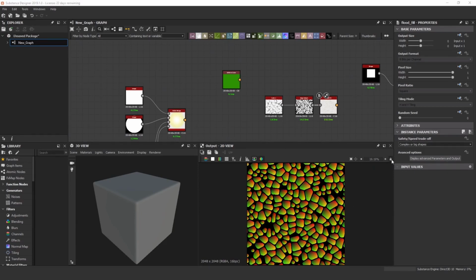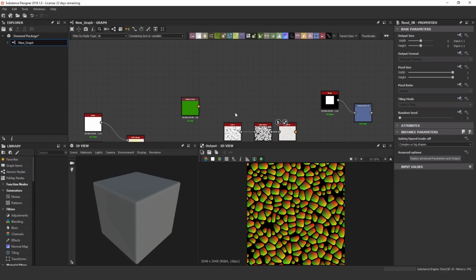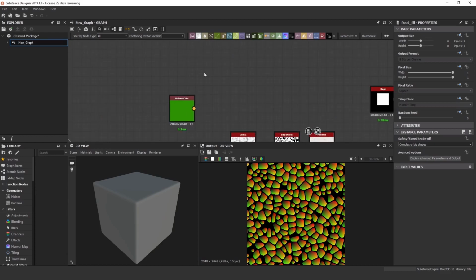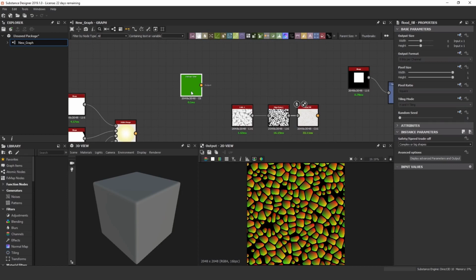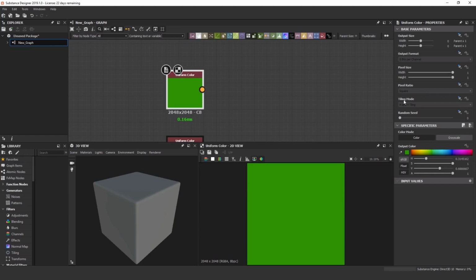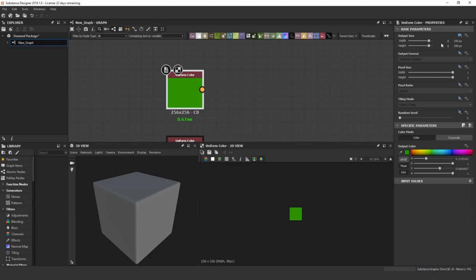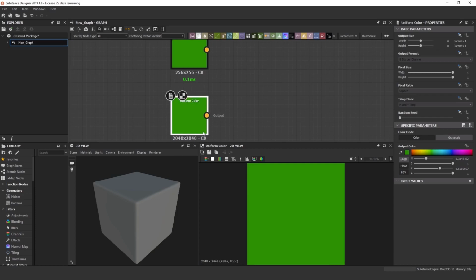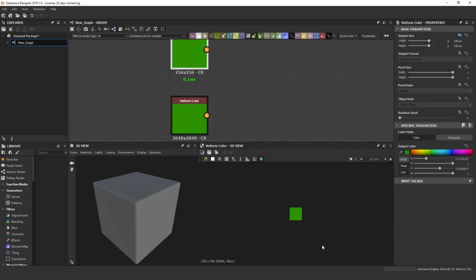And this final button off to the very right, the lock icon, is super helpful when working in different resolutions with nodes, like we talked about in the previous video about changing your node sizes. For example, if we took this same uniform scale and changed the resolution of it, going into the output size, doing absolute, and changing it to, let's say, 256 by 256, you'll notice that every time we click a different resolution, it tries to give you the actual resolution inside of the 2D view.